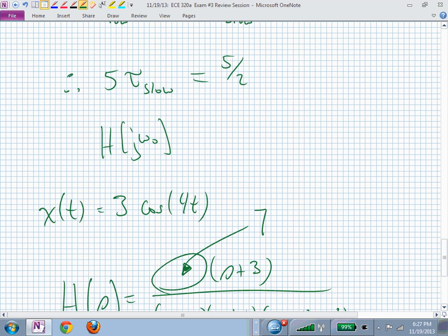Questions on that? Are you getting comfortable with these transfer functions, the poles and zeros, what you can do with them? They're very powerful. Yes, sir. So the DC gain is the same as H of 0. You're saying S is my frequency. And if we want to get it for a lot of frequencies, we replace S with j omega and we walk up the imaginary axis. But if we stepped right at the origin, that's J0, that's the same as 0. So the DC gain is H of 0.